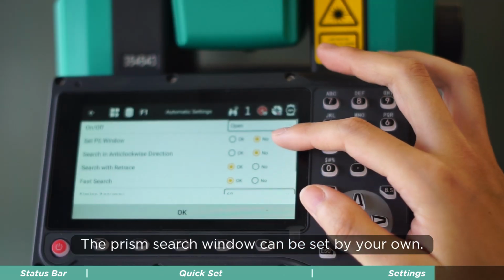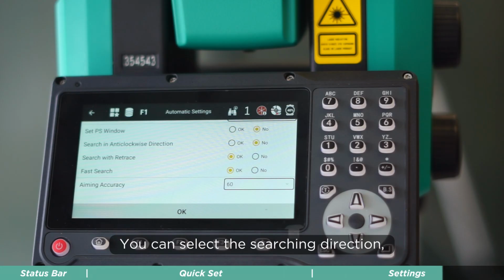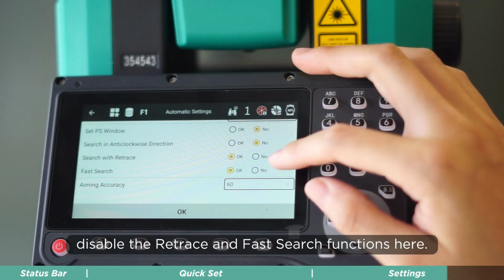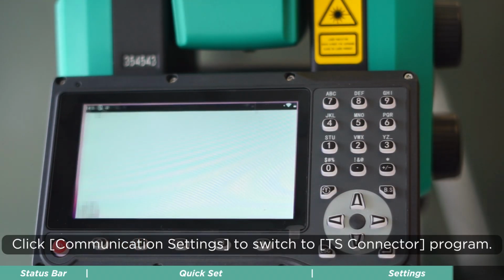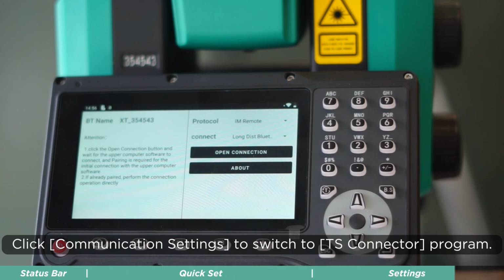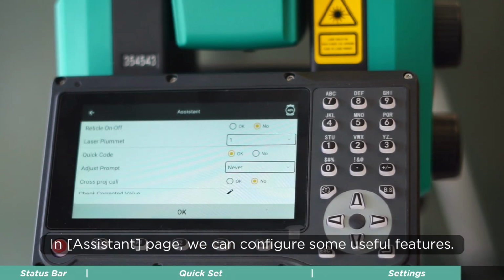The prism search window can be set by your own, including the searching range, minimum and maximum distance. You can select the searching direction. Disable the retrace and fast search functions here. Click Communication Settings to switch to the TS Connector program. In Assistant page, we can configure some useful features.